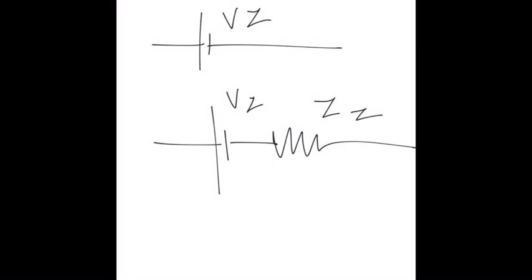The AC equivalent circuit is used in situations where the Zener current is varied by small amounts. It must be understood that these equivalent circuits apply only when the Zener diode is maintained in reverse breakdown. If the device becomes forward biased, then the equivalent circuit for a forward biased diode must be used. By this, we end the Zener diode topic.